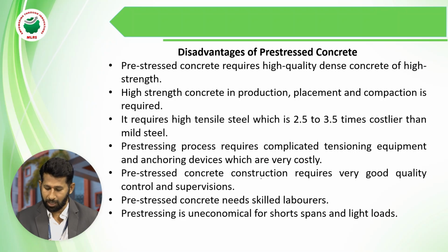Prestressed concrete construction requires very good quality control and supervision. It needs more skilled labor. Prestressing is uneconomical for short spans and light loads. So these are the main disadvantages of prestressed concrete.